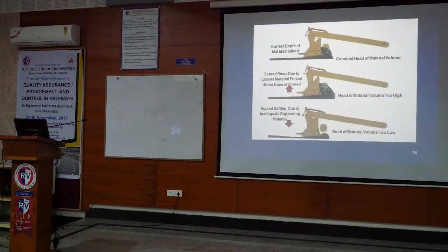During paving also, the load on the screed should be uniform, preferably up to the middle depth of the auger. The paver auger is rotary. The mix should be at the auger's mid depth. If there is mix in the paver, the auger should be at mid level. Any mixer for that matter, be it a pug mill or any mixing unit.